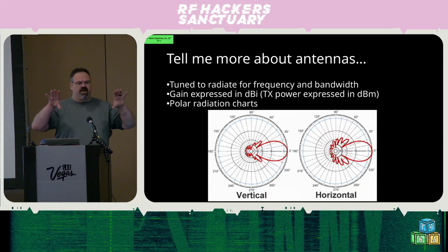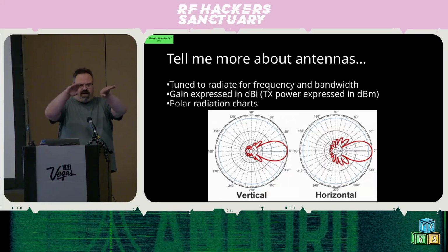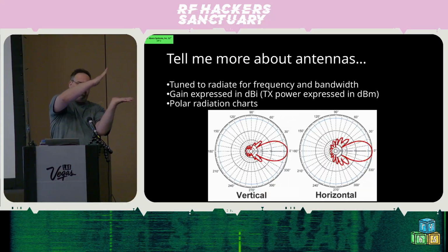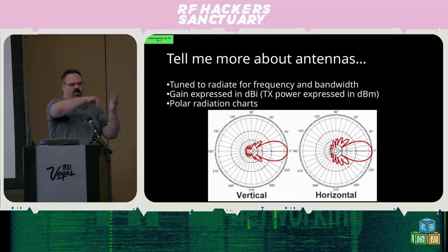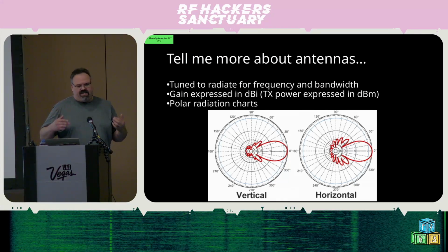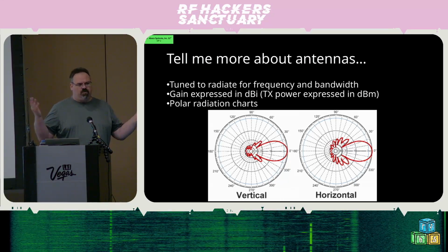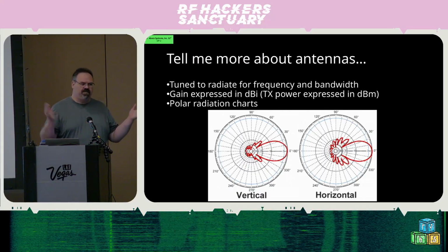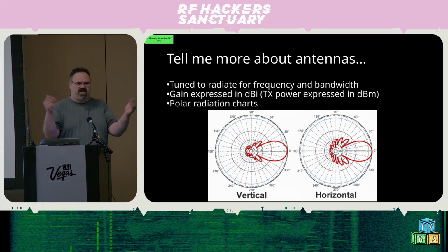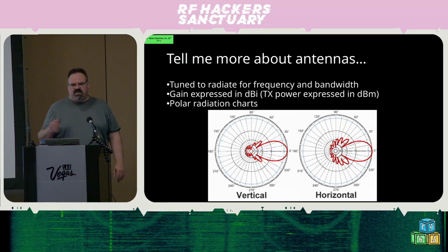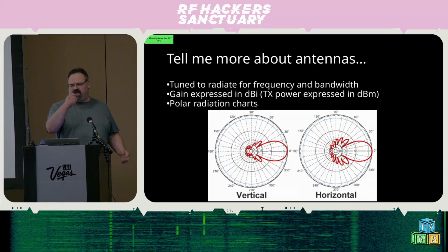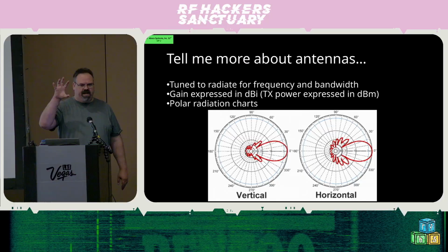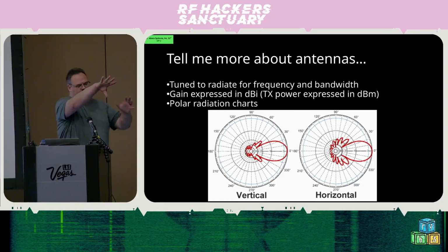So it's putting a lot more signal out in a smaller, vertical chunk around the antenna. As you increase gain, you get more signal, but in a more focused direction. You don't get something for free. Kind of like take a light bulb, light it up, it lights up the room, put a reflector behind it, and it lights up a big spot, but the rest of the room is dark.